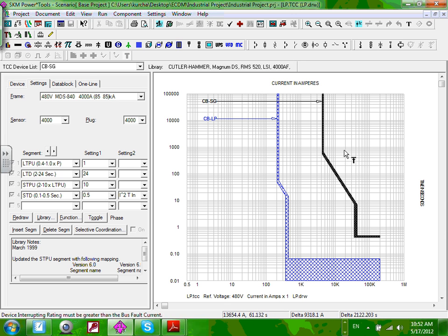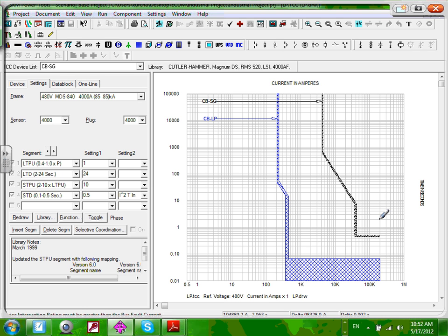This is graphic, it doesn't mean anything until you put it in a report and give it to the electrician so they can install it, right? So what means a lot is these guys. Let me see if I can highlight this. Before I forget, the most important thing is right in here. Can you guys see that? That's the settings they're going to give to Mr. Electrician. It comes in a report. You give it to the electrician, that's how they tweak the circuit breaker to fit.